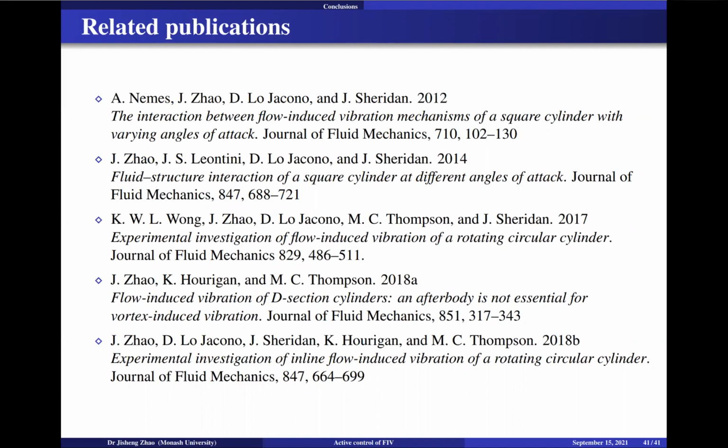You mentioned near the start about the Reynolds number and that it was sensitive in some experiments. So your Reynolds number in your lab experiments is something like 1,000 to 20,000. How would that match up with one of the applications, say the renewable energy extraction application? Is that a similar Reynolds number? It could be slightly higher in real applications because here we have a cylinder with a diameter of like 30 millimeters, but I think you can scale up a little bit more.